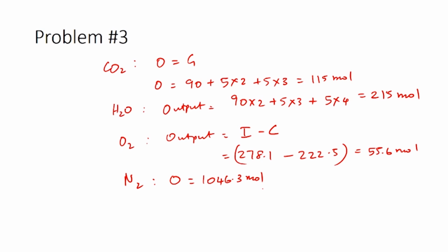We know that this stack gas is coming in at 1000 degrees Celsius. So, now our next step is to perform the energy balance calculations for the waste heat boiler. Since all these gases are combustion gases, we can use tables from textbooks or reference books where we can get information about the enthalpies for these gases. Table B8 in Felder-Rousseau, which is one of the prescribed textbooks, actually has these values, and we can directly use them for performing these calculations. For using table B8, we need to use the appropriate reference state.